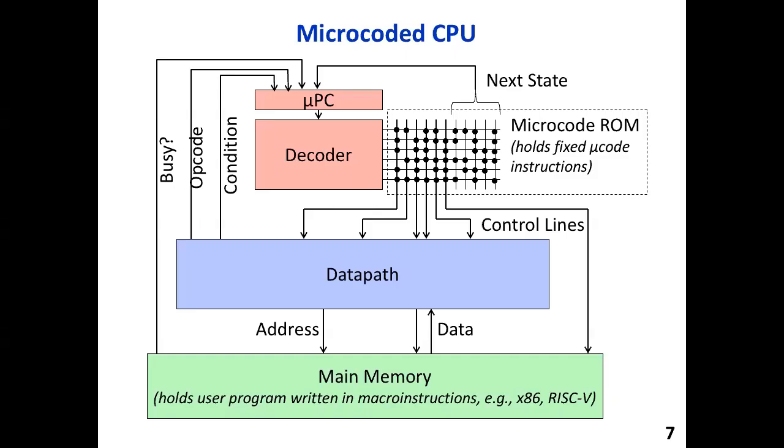So when we think about our decisions about which instructions are important, hopefully we've decided to profile a number of compilers and looked at the instructions that were created, and we were able to make a decision that 128-bit floating point multiplies are used so infrequently that we won't have a direct implementation of those. But maybe we need 32-bit multiplies and we don't need 64, and we certainly don't need 128. And if you're thinking, well, all right, let's do the whole thing with a 32-bit machine, you've made a decision. You can't multiply in hardware the 64-bit numbers.